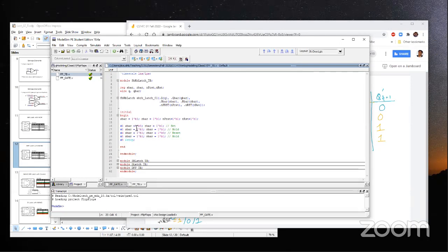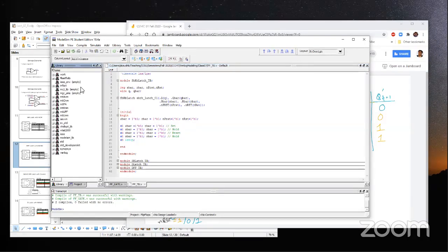And we are supplying these different conditions: set, hold, reset, hold, etc., where we are keeping the preset and reset at 1, meaning we are not presetting or resetting the circuit up front. We are just putting the whole circuit under normal condition. So we compile it, and we load this SBar RBar latch TB.